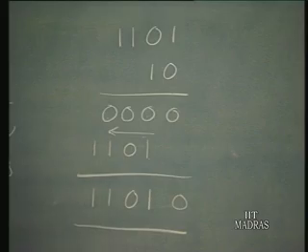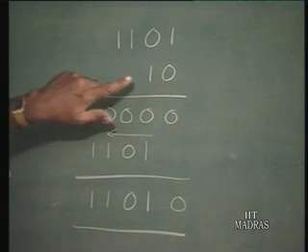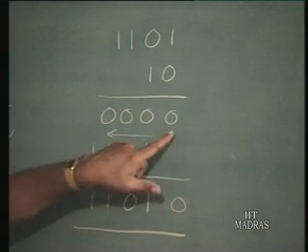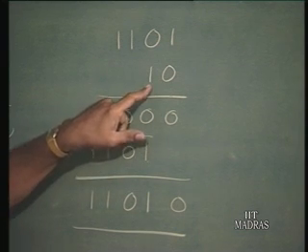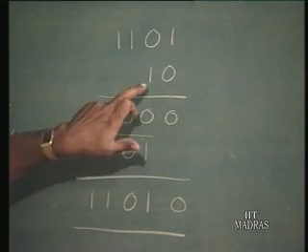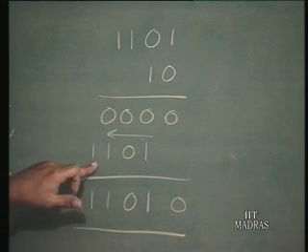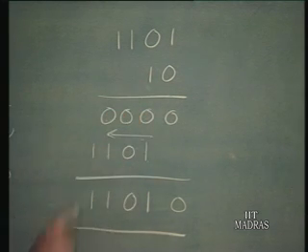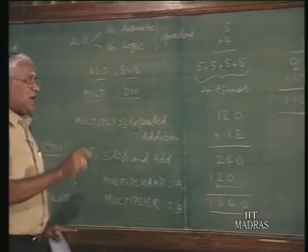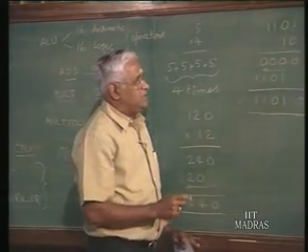Compared with non-binary multiplication, it is easier. Why? If the multiplier bit is 0, the intermediate product is 0. If the multiplier bit is 1, take the multiplicand, but then depending on the position of the multiplier bit, you shift as many places. With this particular one you just have to shift by 1 bit and then you add. You can work it out for other numbers, fine. Once you have this algorithm, then there is no problem, agreed.